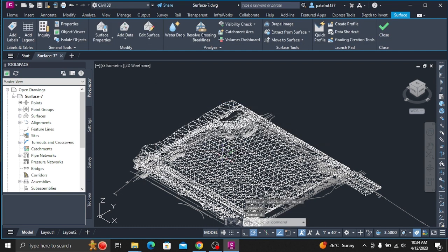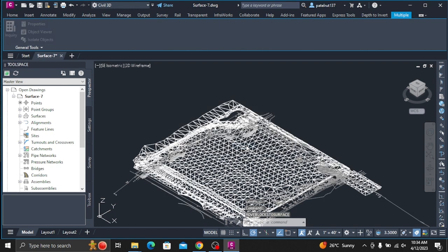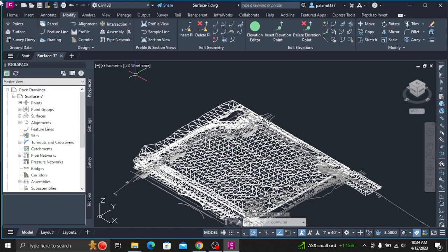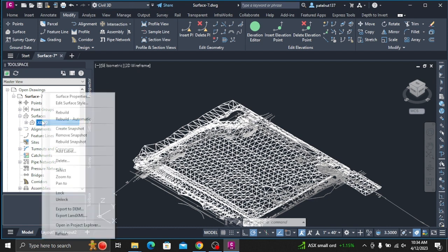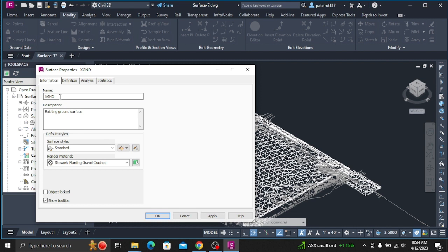Render the surface. On the command line, enter RPREF. Examine the many render settings that are available, including variations in image quality and output size. If you wanted to save the rendered image to a file, you would click and use the Output File Name control to specify a file name and destination. Click. The surface and blocks are rendered in the render window. The effects of rendering are more apparent in a drawing that has different render materials applied to several surfaces and objects.